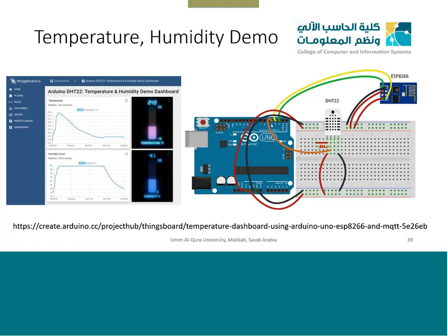It is connected. It will automatically read that voltage, and a program will convert it. That program should be written by you or from a library. It will automatically convert this signal into a temperature value, and from there you can connect using this ESP8266 IC, send this data using the blue and the green and the yellow wires to this device, and this device will connect to your router or your server, and it will automatically send this data to your server.